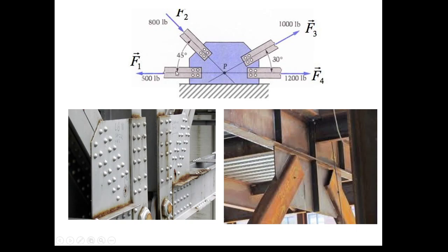okay, using the inclination angle of such a line, saying such a line, I mean it is the line which joins the centroids of the cross sections of the member, and then accordingly load the member, its line of action coincides with the line which joins the centroids of the cross sections, then we can use the inclination angle of such a joining line as the orientation angle for the member. And then if you use the angles for each, then we can guarantee to have the lines of action of the forces, okay, applied by the members intersecting each other at the same point.